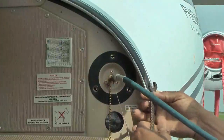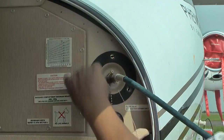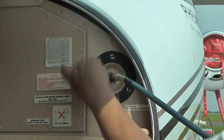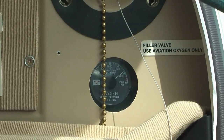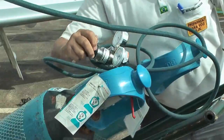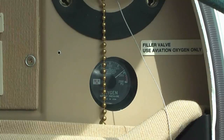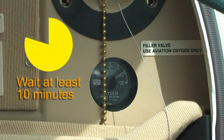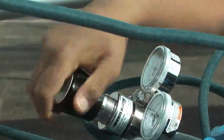Connect the oxygen charge adapter to the oxygen servicing regulator. Connect the oxygen charge adapter to the fill valve and make sure there is no leak. Monitor the pressure gauge of the aircraft and of the high-pressure oxygen servicing regulator. Wait at least 10 minutes to let the temperature of the oxygen cylinder become stable.